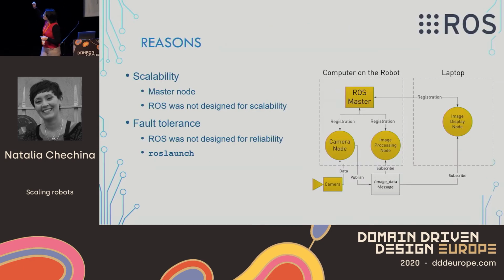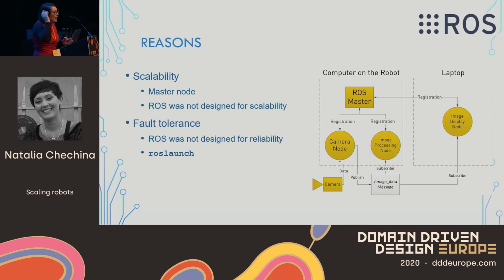And these are some characteristics that you can use to draw conclusions about the scalability of ROS. So first of all, we have the master node, right? Single point of failure immediately. So we need to register everything, and if the connection is lost or something happens with the registration, we need to restore that, and by the time the ROS master node realizes that, lots of time passes. Another thing is what happens if a ROS node fails altogether. That's another problem. Fault tolerance.